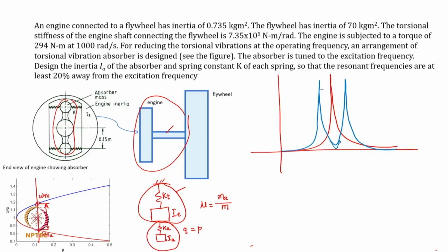But it would be important to look at this frequency range. If it is too short, which is typically the case, and your operating speed fluctuates, then what happens is that although you have designed it for this speed, because of the normal speed fluctuations that can happen in practice, you can actually get into large amplitudes because of the closeness to the two new resonances. So, this becomes a challenging part in this case.